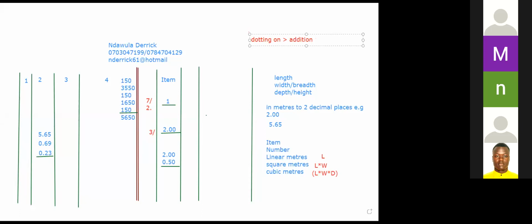So you can see here, for example, there is a 3, and if it was subsequently found that a 4th bed of concrete of the same dimensions was to be provided, then a further one could be added in the timesing column, the process known as dotting on. That is 1 times 3, implying 4.